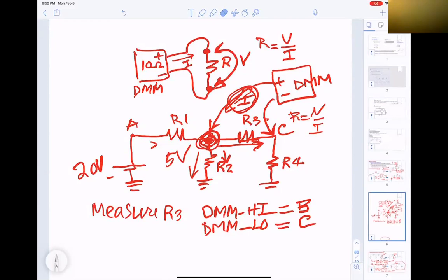In my experience, the best approach to troubleshooting is to take voltage profiles and compare them with the schematic. That's the best way. I just bring it up for you guys to understand. When you're testing the circuit board, you cannot do anything on that board, except say, I found R1 is not working, then you have to replace it.